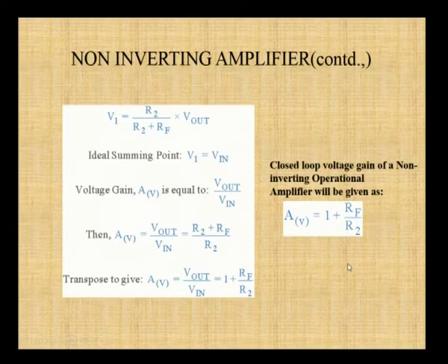So here, if we make the resistances Rf and R2 equal, as in the case of the inverting amplifier, we cannot say that this non-inverting amplifier is going to produce a gain of 1. It is not going to give you the voltage as the input voltage, because the gain is always greater than 1, since in the output equation it is 1 plus Rf by R2.